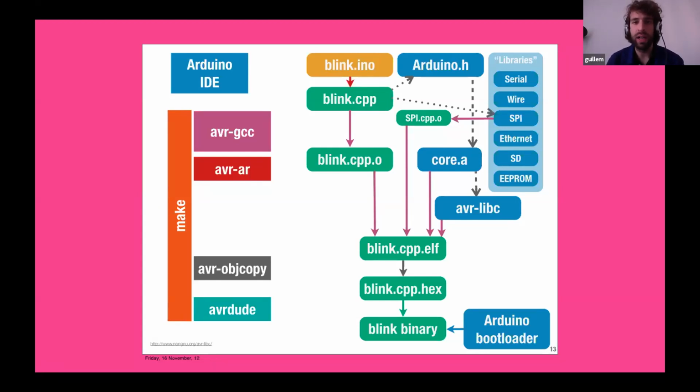And this happened just because when we compile the code, to transform this into C++ code, we add a header file, we add a library that's called Arduino.h. So the same, if you ever use Arduino and you load a library to do something like driving some LEDs, or a library for managing a servo motor, or a library for reading a specific temperature sensor, you load a library on top of your code that was called maybe Wire, or NeoPixel, or SD. The same, under the hood, the Arduino IDE or PlatformIO or whatever compile chain you are using, it's loading this Arduino header inside your Blink file.